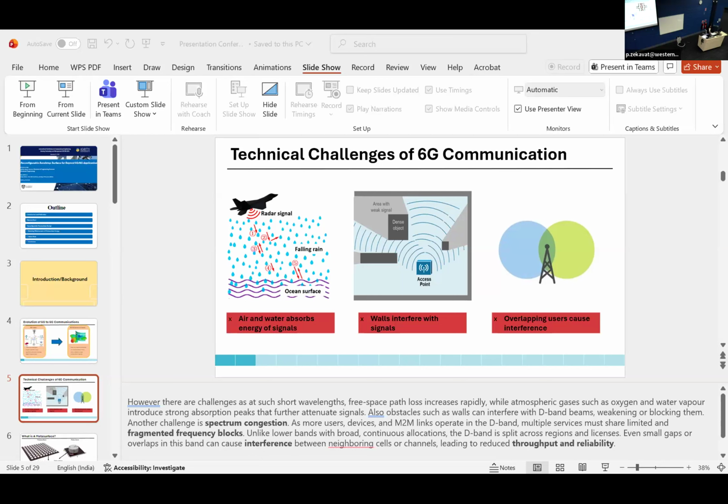Under transverse electric polarization mode, there are three modes observed, where the first one focuses on the Q band and finds a shift from 12.64 to 14.75 gigahertz. Mode 2 focuses on the C and X band spectrums and finds a shift from 6.62 to 11.28 gigahertz. And then mode 3 focuses on the X band spectrum and finds a shift from 9.82 to 11.63 gigahertz.